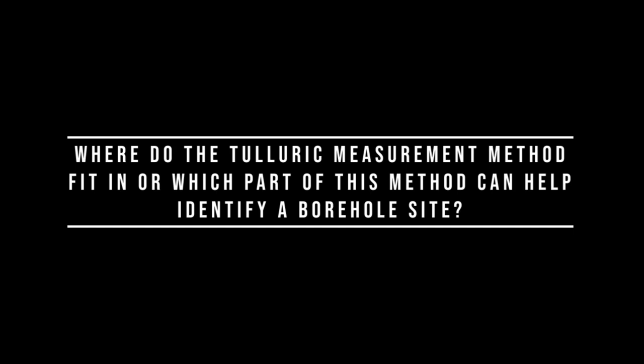So the PQWT method is still relatively new in the groundwater fraternity. It still has to be proven. There's questions behind how it collects the data and what the data actually means. We have tested it, and we had small issues with battery life and when working in temperatures above 35 degrees. And often that's the issue. If you've got the best equipment, it's got to be reliable in tough areas, remote areas where we often find ourselves. It is a very interesting method, and it looks like it has great potential.